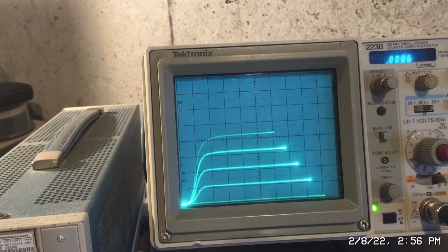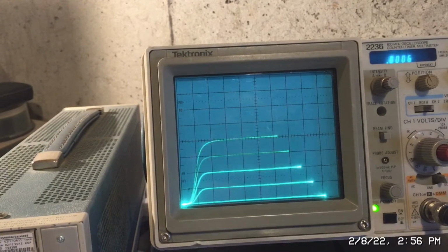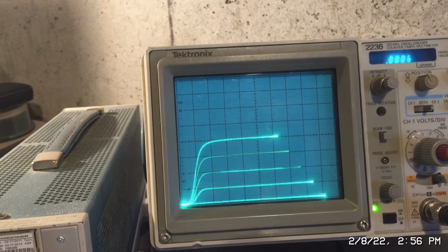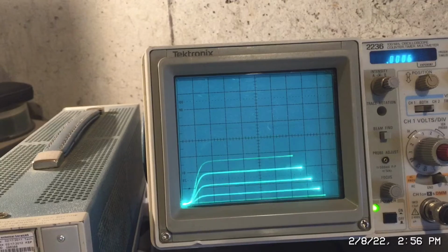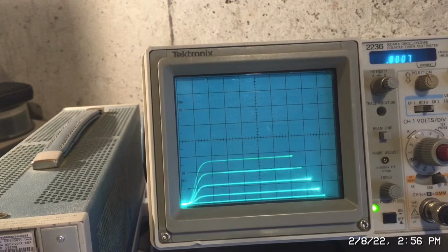Okay, not bad. So let's take another Fairchild transistor and plug that in the socket. Let's compare this one. What do you see there? You see that for the same transistor, same manufacturer, the gain is actually much lower. So let me change the resolution back so we get a little bit more accuracy in the measurement.